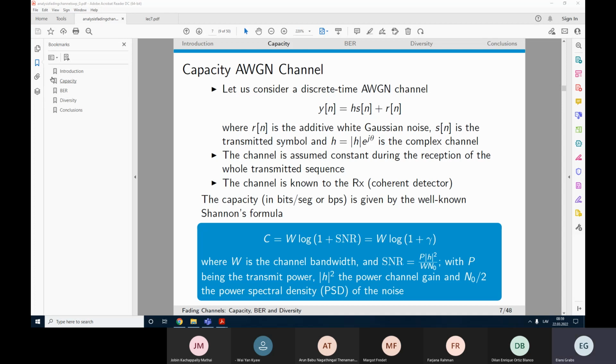So here we have a reminder of how to calculate channel capacity for the channel with noise according to Shannon's formula, where W is the bandwidth of our signal, which is limited by the filter we are using, and SNR is the ratio of signal to noise in times, not decibels, so it's converted to relative units.